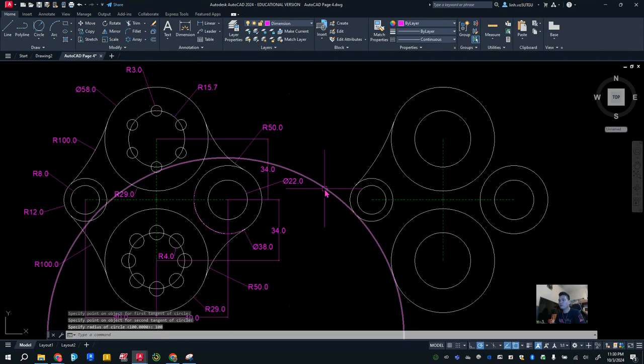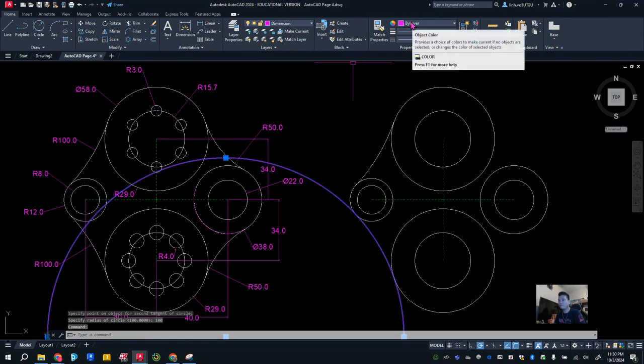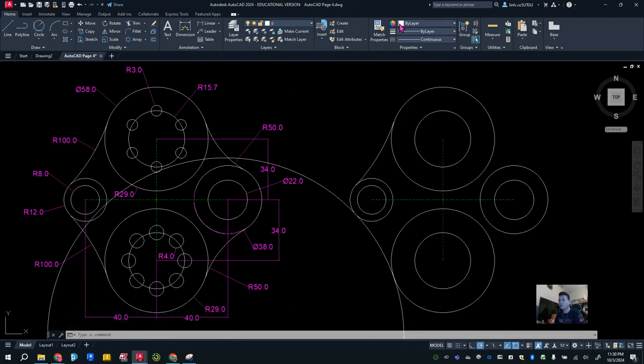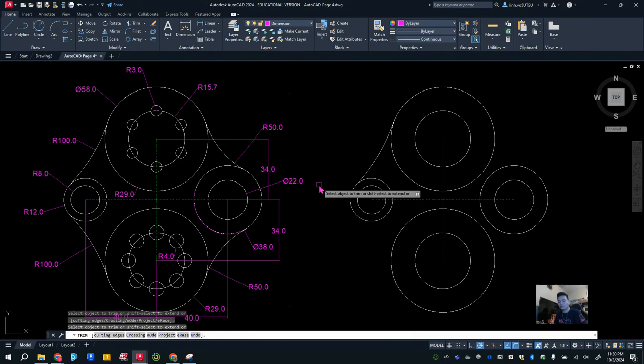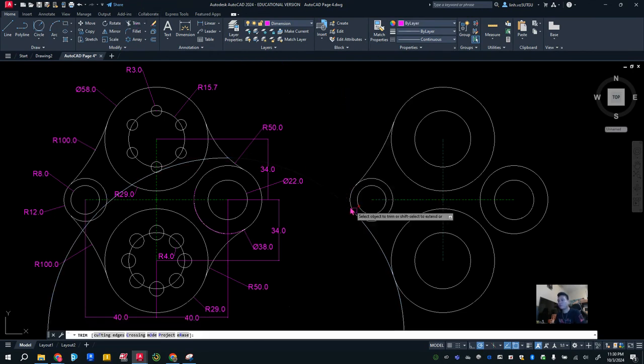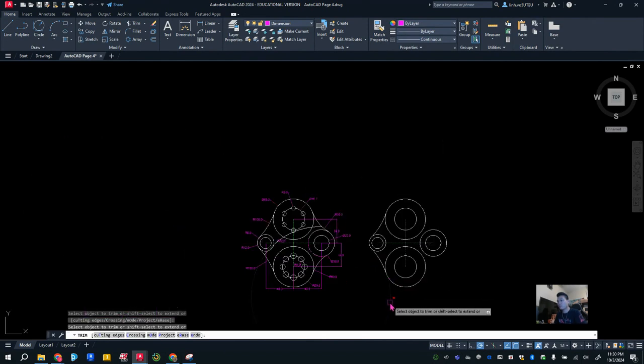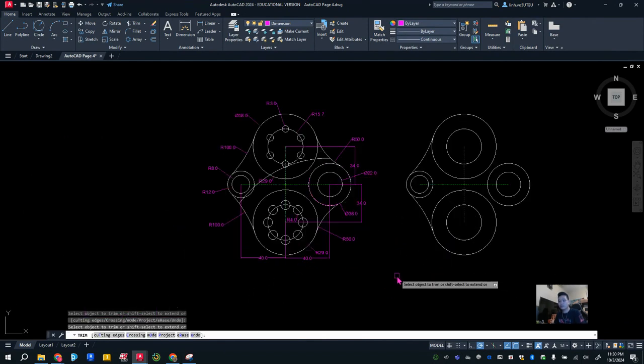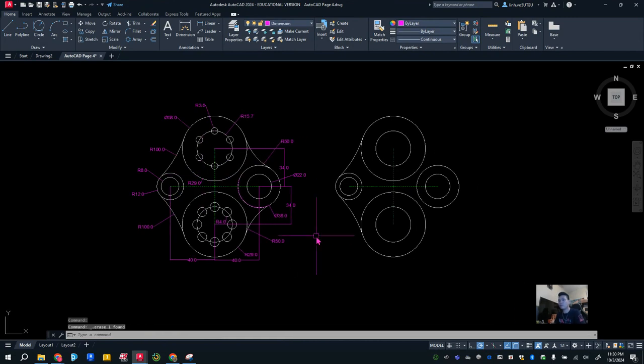The same thing, and again, I need to be in my drawings layer. I'm gonna trim. Control, hit escape, and then now let's try trim again one more time. See if that works. All right, it should work. And then we're gonna click on this, delete that from the drawing. Then we'll continue to the one on the right hand side.